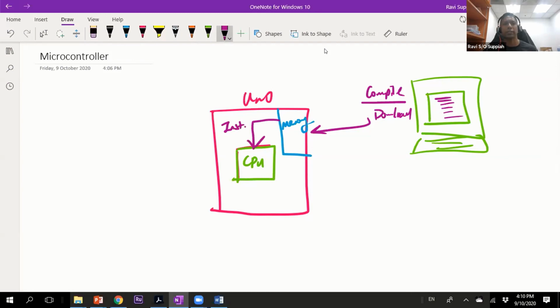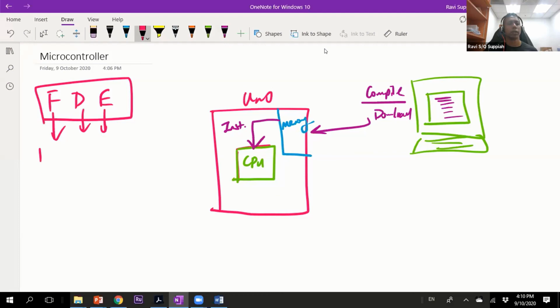Each instruction is telling the processor to do something: turn on this GPIO, or fetch this data, or add this number to that number. So it is some instruction you are fetching. You fetch, you decode the instruction, and execute. If you look up any material, they will usually express it as 3 different main operations. We call it the fetch, decode, and execute cycle. These are the 3 main things that any processor will do for us.